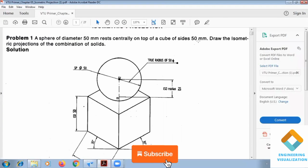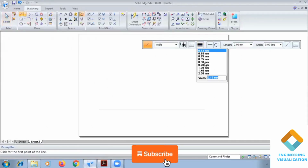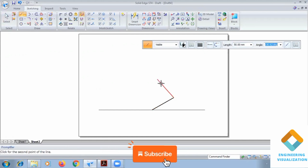So this cube of sides 50 mm. 50 mm means we need to consider a 50 mm box. So here please consider the angles. From this reference end, length will be 50, angle is 30 degree. Again length is 50, angle is 150 degree. Then again length is 50, angle is 210 degree. So like this we need to construct the box.